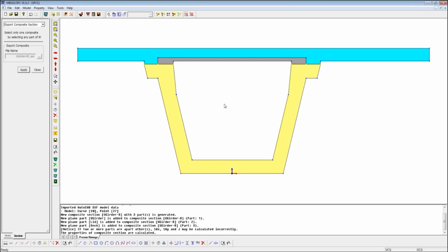And to consider the haunch, if you really want to consider its load, and you want to be accurate in the dead load effects, then you can consider the weight of that haunch onto the structure as well. So in that manner, you can consider the variable cross-sectional properties due to the different haunch heights. Therefore, it is hard to find a platform or a spreadsheet that will consider all those variations.